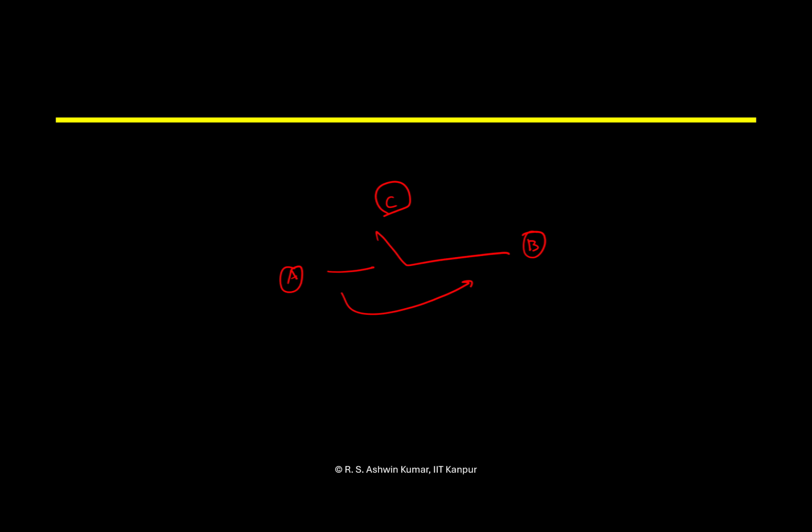And for me, the first wow moment in circuits came when I related signals and systems I learned in second semester to a circuits course I learned in my third semester. So in signals and systems, I learned that Fourier told centuries ago that if I have a square wave, you can decompose it as a summation of sinusoids. And in the circuits course, I learned that an RC circuit acts like a low pass filter, filtering sinusoidal frequencies. So that made me think, what if I pass a square wave through a cascade of RC filter sections? I tried that during a lab session. I found that square wave input gives sine wave output. It was a wow moment for me.